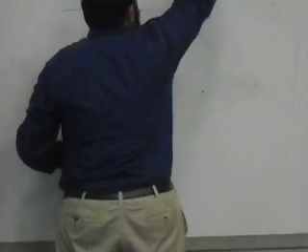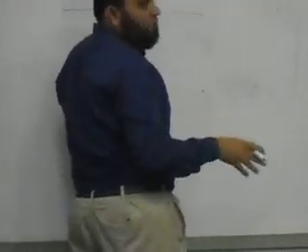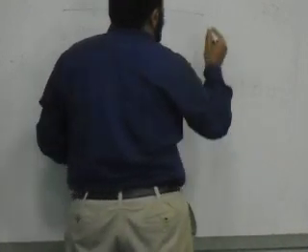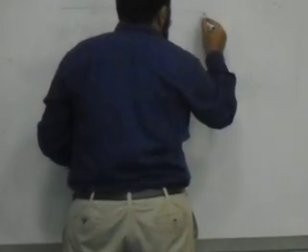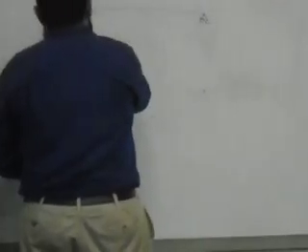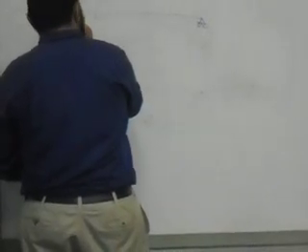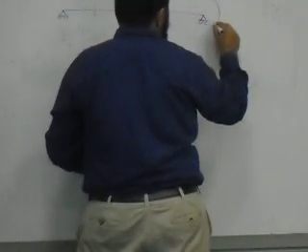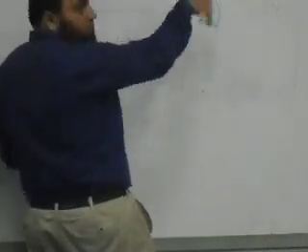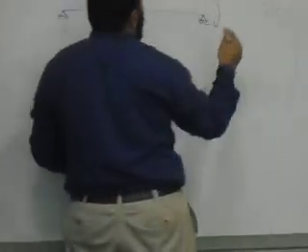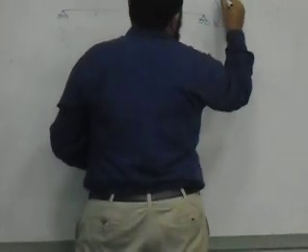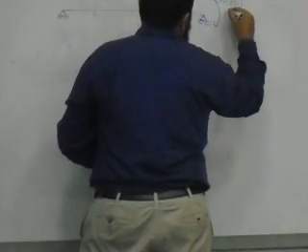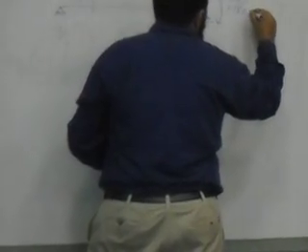So let's start with this one. 30K at a distance of 6. So that means in terms of moment, it's what? What's the moment? Yes, bravo, 180, which is 30 times 6. So I'll have a moment like this, depending on the arrow, it wants to rotate like that. I'll have a concentrated moment here of 30 times 6, which is 180 kip feet. Bravo.